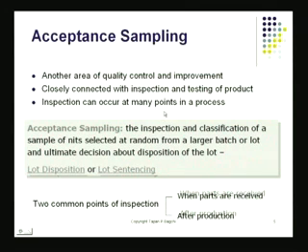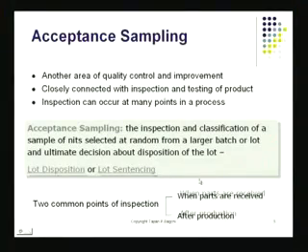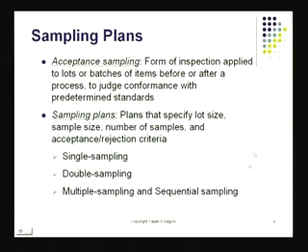An inspection can actually occur at many points in the process. For example, when you've got incoming parts, parts which are just arriving from a supplier, you could inspect them before they enter your shop. And after you've done your production, when you're making your shipments, at that point you could again do your inspection to make sure that the parts you supply to your customer are of acceptable quality. So in fact, there are two places you could do acceptance sampling. One is when the parts are received, and the second is after production, to make sure what you ship out is within the acceptable quality level.